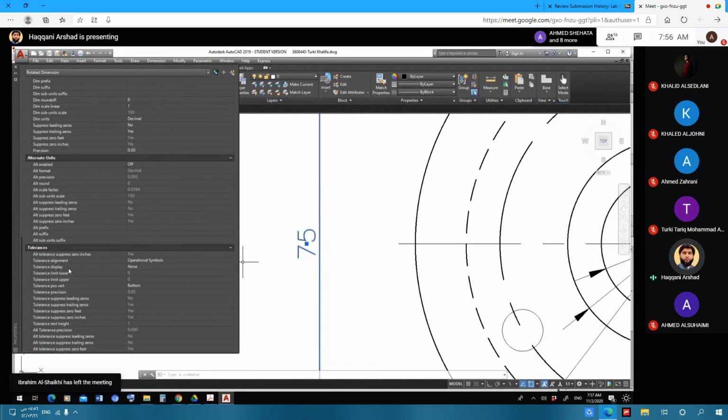In the tolerances, you have some options, we have four options: symmetrical, deviation, limits. You see, if I select symmetrical, it will come in this way, plus or minus. If I put deviation, it will come separately, plus separately, minus separately. If I put the limits, it will calculate by adding up the upper limit and subtracting the lower limit, the basic size. So likewise, now we need it here in a symmetrical fashion. So we go for symmetric. Okay, and the limit is 0.5.